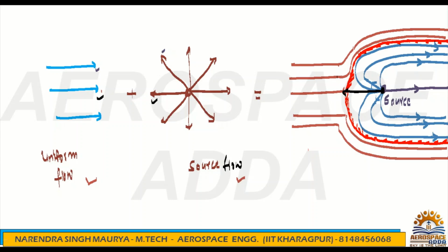Okay. And if you check this boundary, which is also called an imaginary body, it is open. It is open here at this end, and the top and bottom red lines are open. It is not going to close somewhere, because when would it close? When there is another sink, all the flow streamlines would sink towards the sink point. But we do not have any other sink, only the source is available, hence all the streamlines will be open to infinity. It is not going to close somewhere.